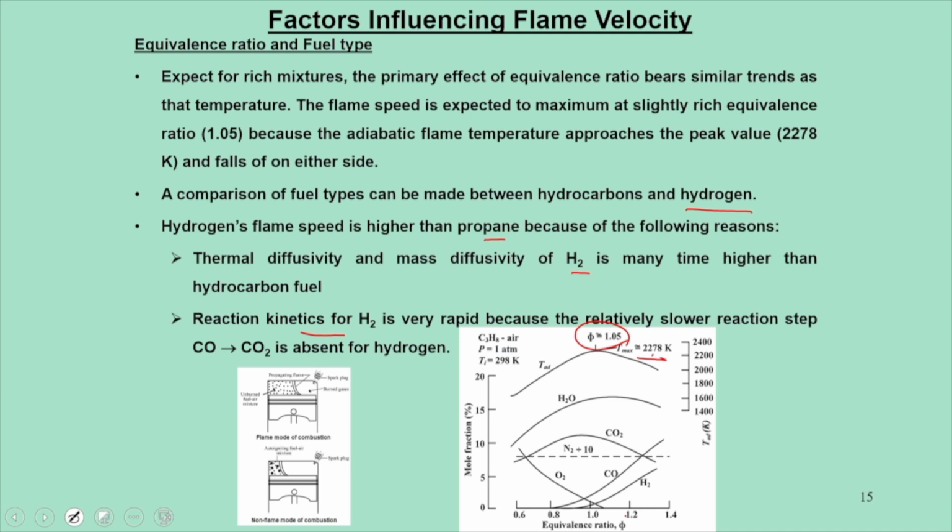We say that in the presence of hydrogen reaction kinetics is faster, and this also helps with NOx formation, because when you have a rapid reaction, the relatively slower reaction is absent, and in fact hydrogen also acts as a kind of catalyst for a favorable situation.